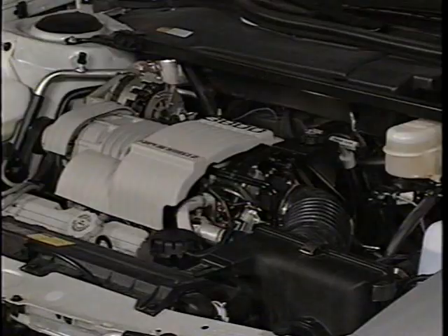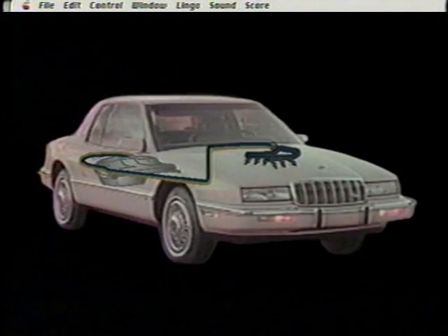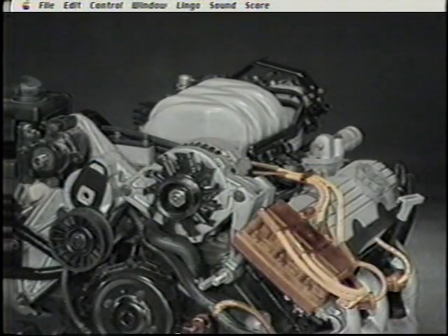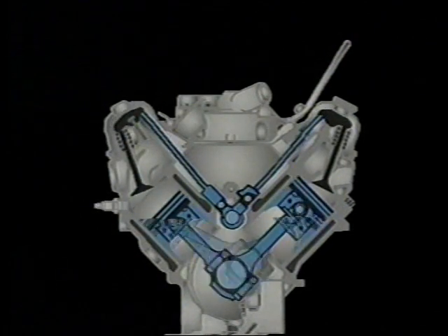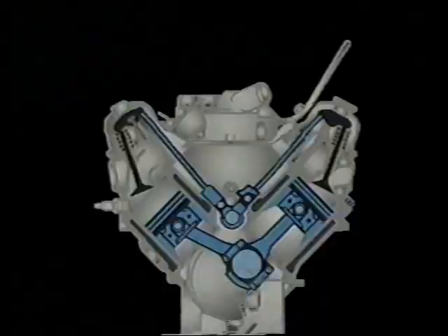When beginning a diagnostic routine to solve a drivability complaint, you should remember the basic systems that make an engine run: the fuel system, the ignition system, and the engine mechanical system, which can also be described as compression and valve timing. Today's engines could also be said to have a fourth area, that of the ECM-PCM and related sensors and output devices.